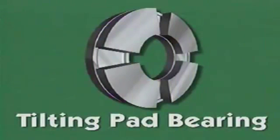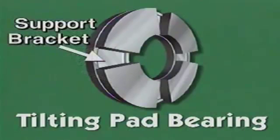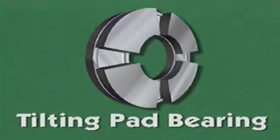This bearing is a tilting pad thrust bearing. It's also called a Kingsbury thrust bearing. A typical tilting pad bearing has two main parts, movable thrust shoes and a support bracket. The thrust shoes are pivoted to allow them to move slightly. The thrust shoes rest on the support bracket. They're held in place by pins on the support bracket that fit into holes on the back of the thrust shoes.